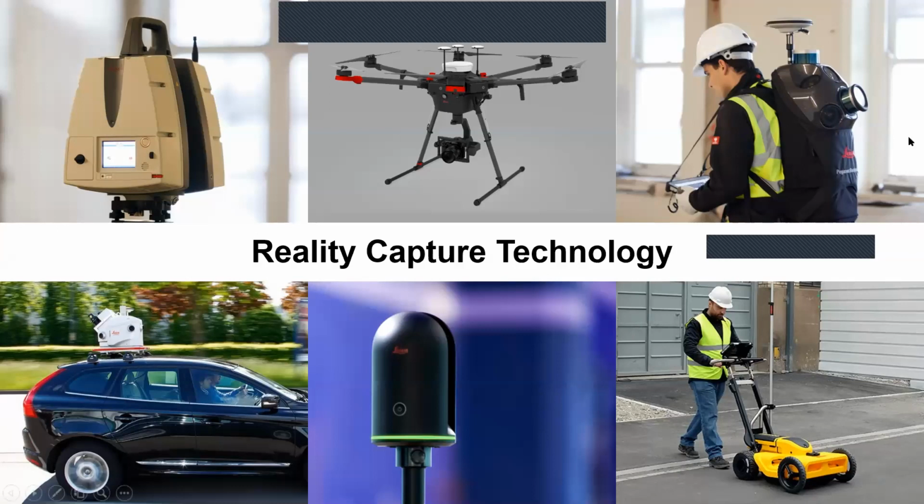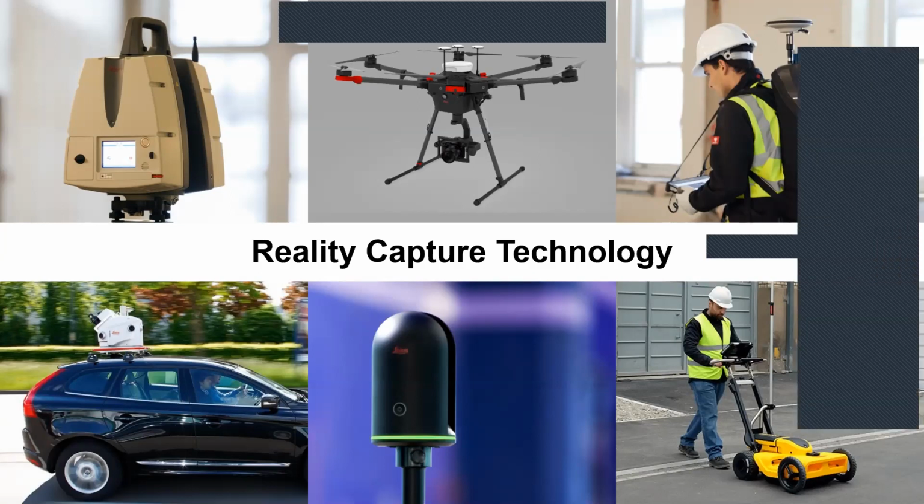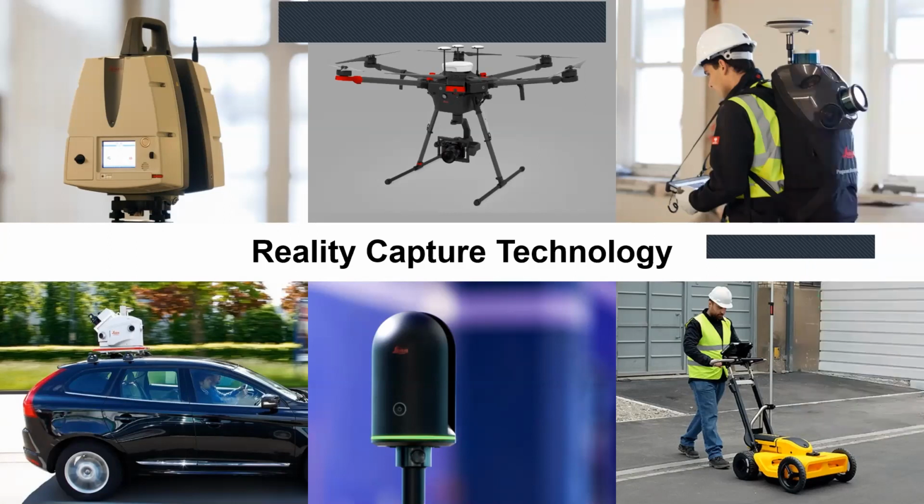Like if you see on the center lower part, it's a BLK360, a scanner which captures just 60 meters with 360,000 points with millimeter accuracy, along with thermal data, which is good for an interior designer or a person who is constructing a building of 3, 4, 5, or 6 floors. So the solution was designed as per the requirement of the customers, with a smaller laser scanner with 60 meters, then 130, then 270, 480, and then a kilometer range.